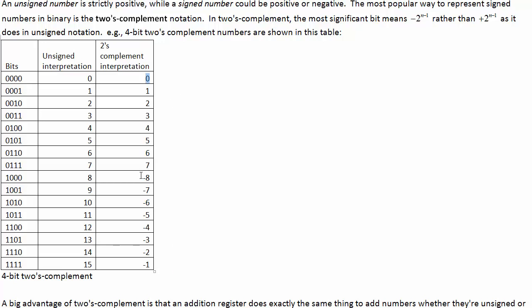On the other hand, look at what's going on here in the middle between -8 and -7. If we take 0, 1, 1, 1 and we add 1 to it, then we get 1, 0, 0, 0, which for the unsigned interpretation says 7 plus 1 is 8, no problem there. But the signed interpretation says 7 plus 1 is -8. That's wrong. We've got an overflow happening. So the overflows happen in different spots in 2's complement versus unsigned.